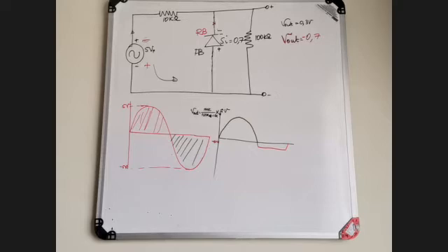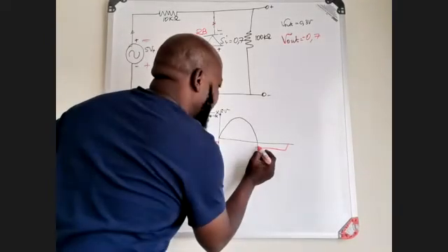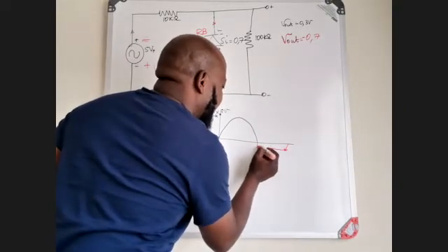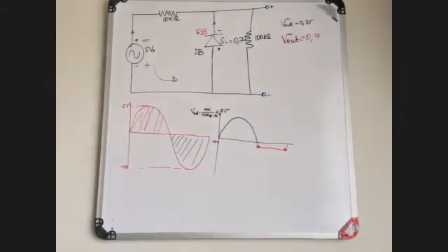When I want to increase this clipping off, I must increase it in a manner whereby I need a constant DC voltage. Now, where's that DC voltage? You will see that here, at those 2 points, that is where you have got your DC voltage. I don't want it to be at 0.7 volts, or at minus 0.7 volts.